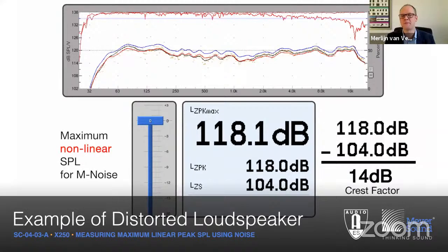And now you see the problem that this standard is trying to resolve, which is that a triple-digit metric in the datasheet does not reveal how the loudspeaker sounds by the time you attain that level. And that is, of course, something that is worth improving. Is the loudspeaker still sounding acceptable by the time you reach that data sheet value or not? And for that, you need to include distortion into your stop metrics, in your stop conditions, besides compression.